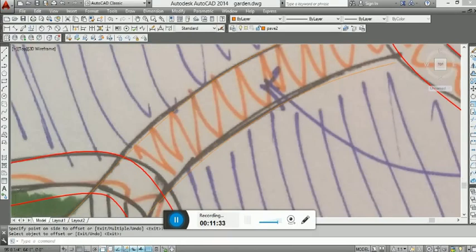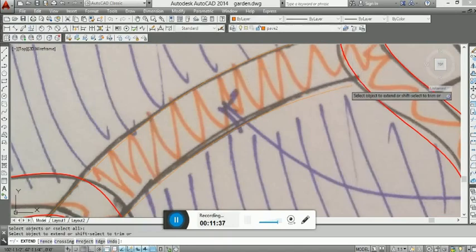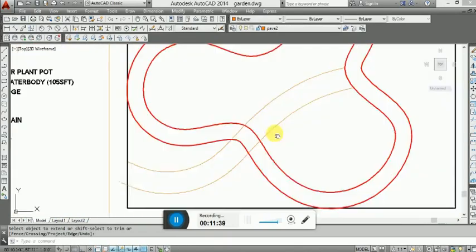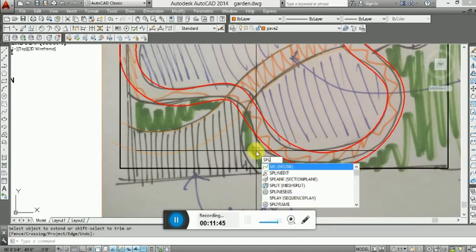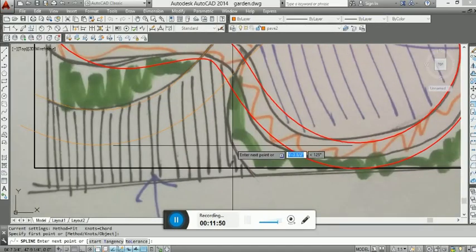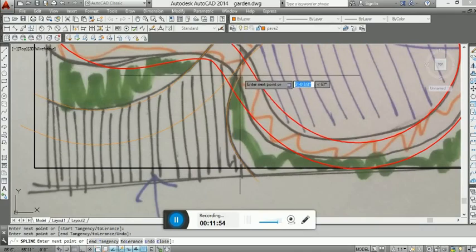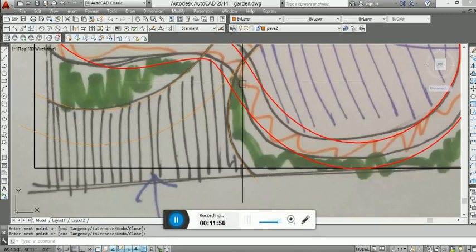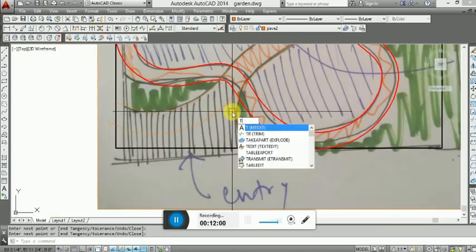Okay, now this line is actually the 4 feet line and matches the drawing, and I can extend it because at the end the line has to be closed if I want to use the hatch command. Now I will draw again with the SPL command to draw this curved line, and I am drawing it following the sketch. You see that I am following all through the sketch line to guide me in what I will draw.